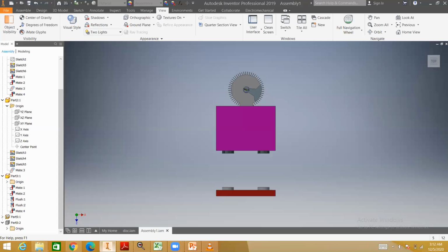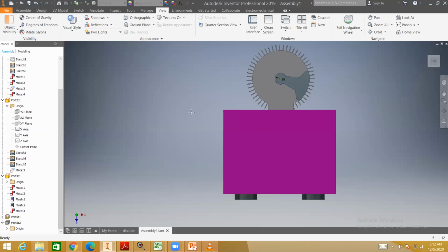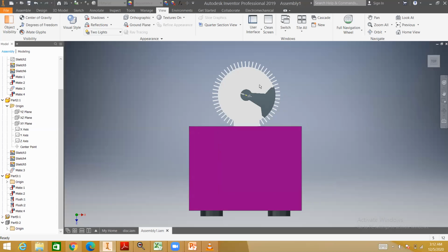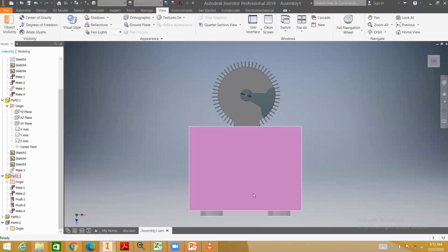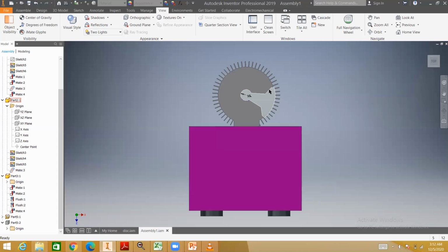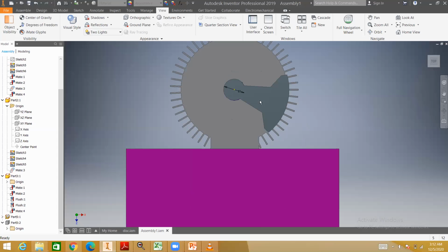So now we will perform the experiment. The first part of the experiment is to find the natural frequency by using the experiment. This is our physical setup. This is the motor which is connected to the mass. This motor has the eccentric mass. This is the eccentric mass. For this mass, there is one center of gravity somewhere here.